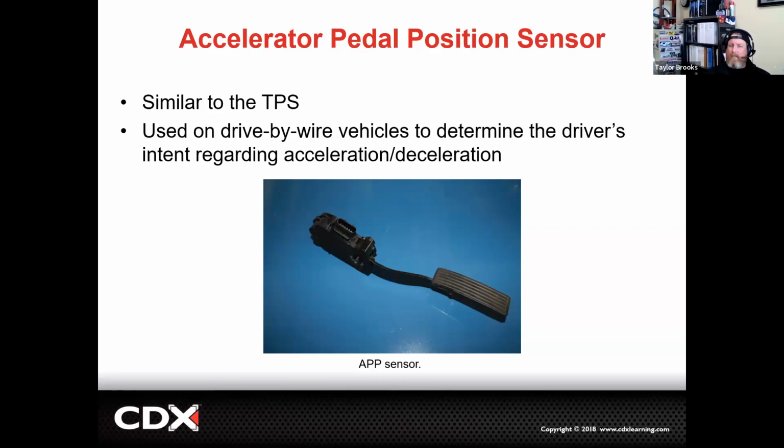I want to make very clear, these systems have been around for close to 30 years now. They are very reliable. It is very rare that I ever have an issue. In fact, for the first time in a very long time, I had a car where I replaced the accelerator pedal and it fixed the car. Normally, they very rarely throw codes and they very rarely go bad. So do keep that in mind when you look at diagnosing these systems. Quite often, we're looking at a wiring issue or a module issue that we need to correct ahead of time.